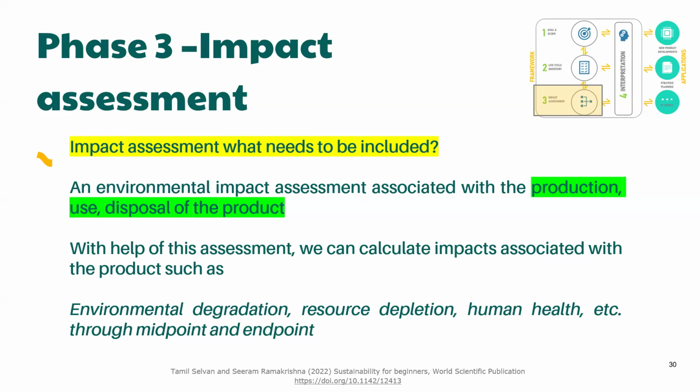So to give you a basic idea, if you focus only on a manufacturing process, for example, your assessment will be different from conducting an assessment for the entire life cycle. So it's up to you to design the LCA study based upon the requirement. You have to precisely define your goal and scope of your selected study, and based upon that, your impact assessment will significantly vary.